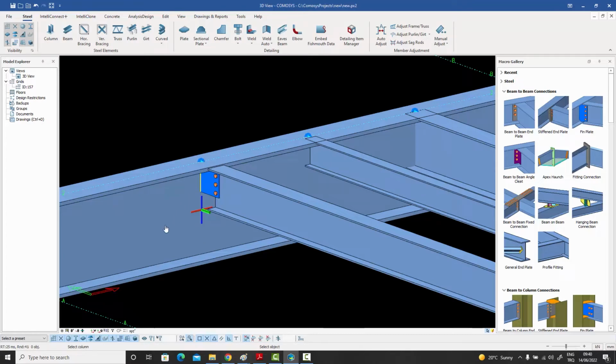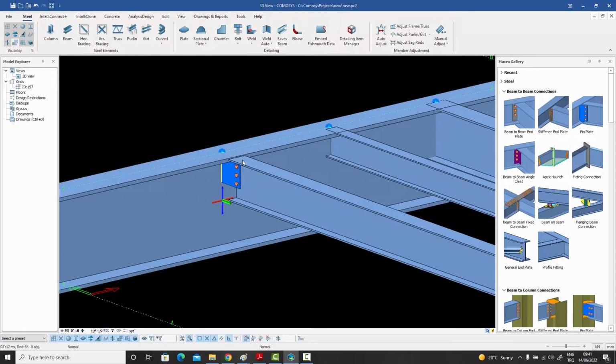And we also have this option of selecting some horizontal bracing which might be framing into the same area, because you might have a situation where you want to include the forces of those horizontal bracing in the analysis. So there are reasons why we do the right click, but in any case, let me right click and finish that.